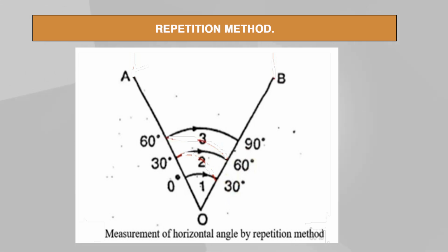This method of measuring angle is known as the general method or the ordinary method of measuring a horizontal angle. Whereas, when we are doing high precision work, or the nature of the survey work needs accuracy as a priority, at that time we adopt one of two scientific methods for measuring horizontal angles. The first one is the repetition method, the second one is the reiteration method.